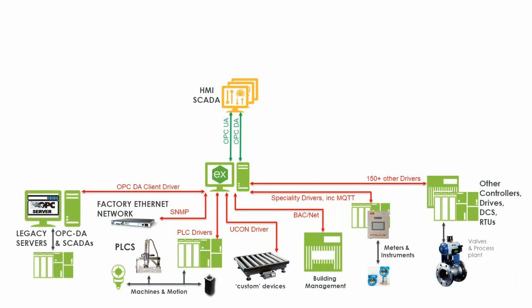The same thing goes for systems that you might have which are legacy type systems. If you have an older instance of a SCADA package that may have been built upon OPC DA, you might have a self-contained machine that has not only a PLC but a SCADA package all within that same PC's control system. You can get data out the back of it using the OPC DA drivers that KEPServer have, so you can tap into older systems, older SCADAs, and pull data out of that as well.